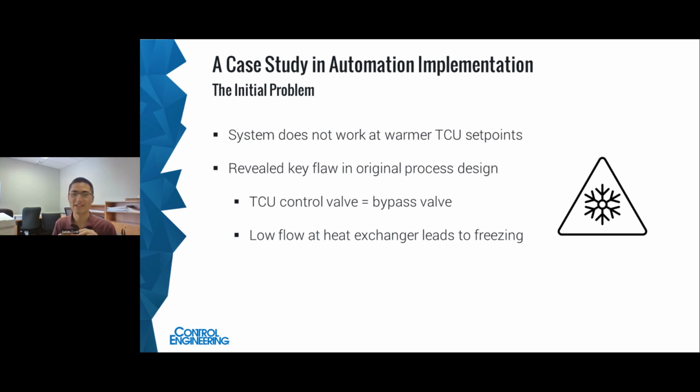And once that happens, all the flow is going from that TCU pump you saw, and it goes straight into the reactor jacket, and it doesn't go down that path to the LN2 heat exchanger. So what you ended up with is a low flow condition there, which eventually leads to freezing of the little amount of heat transfer fluid left in the exchanger. And once things start turning solid for a process like this, then you lose all ability to control the system.